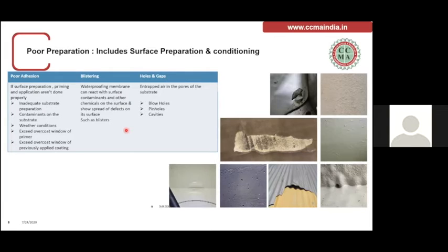While pinholes are more like this: the concrete over which we are doing the waterproofing membrane is regularly breathing. And while we apply a liquid membrane or a fast setting system, while the concrete is breathing, the air pressure acts on the weak liquid membrane, and that forms pinholes. Also, pinholes are seen in membranes when you apply the waterproofing membrane at too much thickness. So that is another reason.